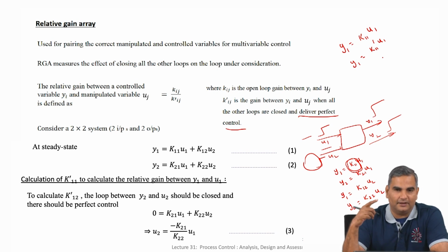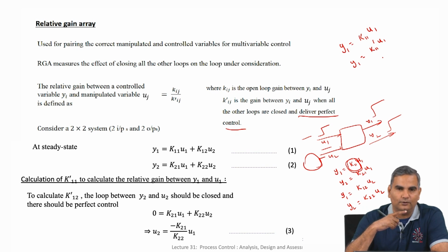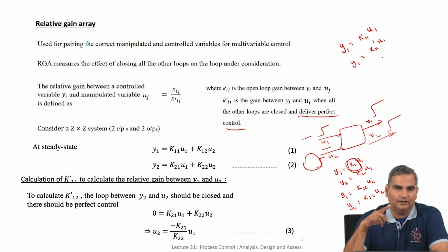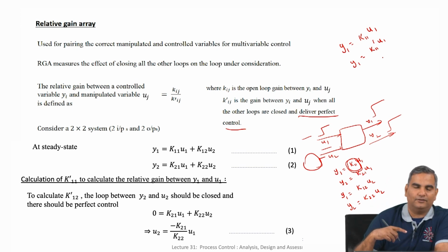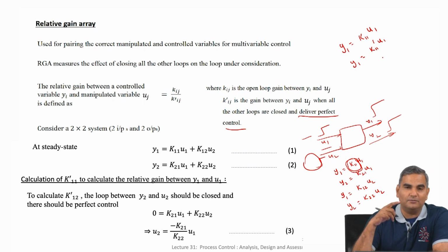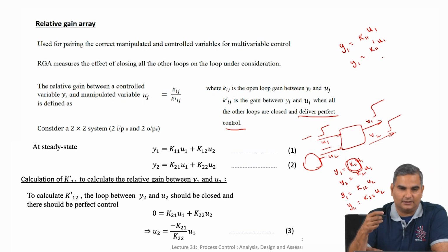Remember in the decoupler, when you had the u1 decoupled transfer function with y1 and the u2 decoupled transfer function with y2, the model, if it were just u1, would have been g11, but the minute we made it u1 decoupled it was g11 minus other terms. The other terms come from the interaction of the other loop. So, in some sense the model itself changes when you look at things in open loop and closed loop. That was a dynamic version of this.